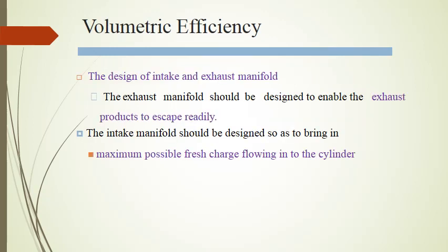The design of intake and exhaust manifolds. The exhaust manifold should be designed so as to enable the exhaust products to escape readily, while the intake manifold should be designed so as to bring in the maximum possible fresh charge. This implies minimum restriction is offered to the fresh charge flowing into the cylinder as well as to the exhaust products being forced out.